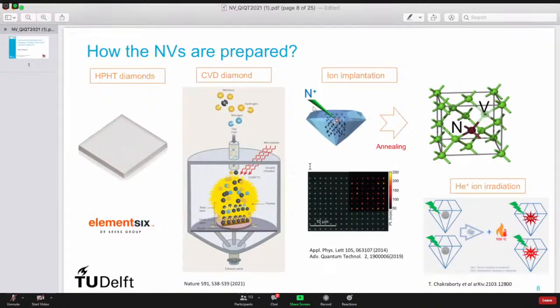And then there is a diamond layer substrate which is kept at the bottom, and the diamond layer gets deposited on the diamond substrate. This is how a single crystalline diamond is grown. And to create polycrystalline diamond, other substrates can be used like silicon or sapphire. Then the polycrystalline or microcrystalline diamonds can be grown.